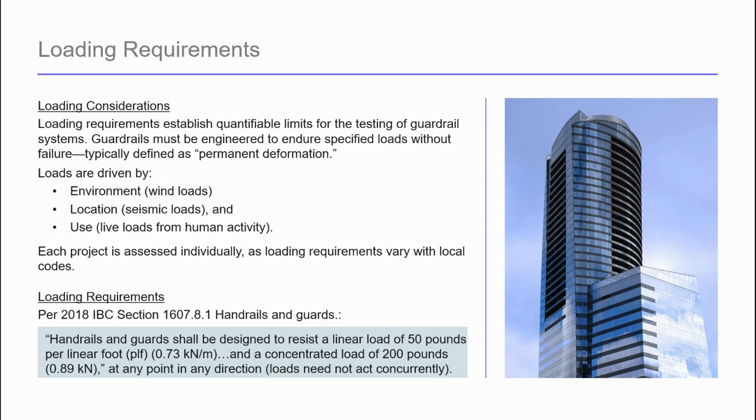For exterior railings, which might see much higher wind loads, you may require a special structural accommodation going down through the slab, for example, down to the steel or into a concrete beam. As stated previously, scheduling delays and costly changes can be avoided by simply addressing those loading requirements early in the design.